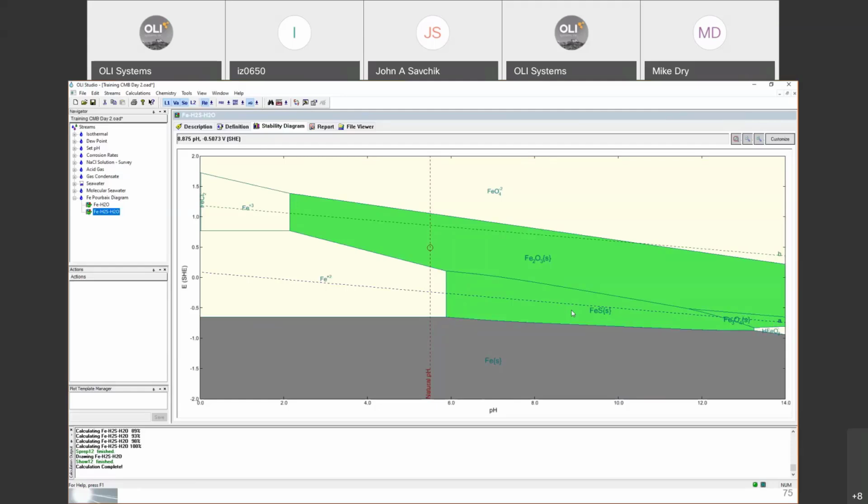But if you remember our first class, we were talking about the options of sulfur and oxidation states, and about redox reactions. In here, the software is only taking into account the redox reactions of iron, the transition metal, and sulfur is being assumed to have the oxidation state of -2. But what happens if, let's say in oil and gas, under reservoir conditions, you have elemental sulfur? You know that at those conditions, you will probably have the oxidation state of elemental sulfur. So we will do an example trying to mimic those conditions, taking into account the oxidation state of -2 and the oxidation state of elemental sulfur.